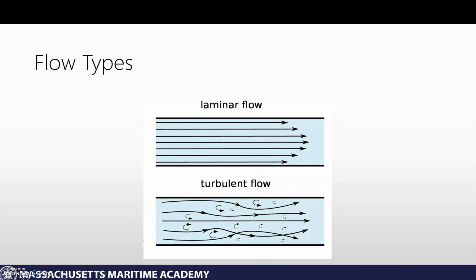So if we look at a sketch of this, here's our laminar and our turbulent flow. Once again, orderly. This is a big thing about laminar flow. You can see it's all in straight levels. It's all in just little chunks. It looks great. Turbulent flow, chaotic. I can't spell chaotic today. Chaotic flow. Things are going crazy. It's moving around. You see streamlines are crossing each other. We have a bunch of weird little eddies and twists in it. And that'll make things kind of interesting to calculate out.